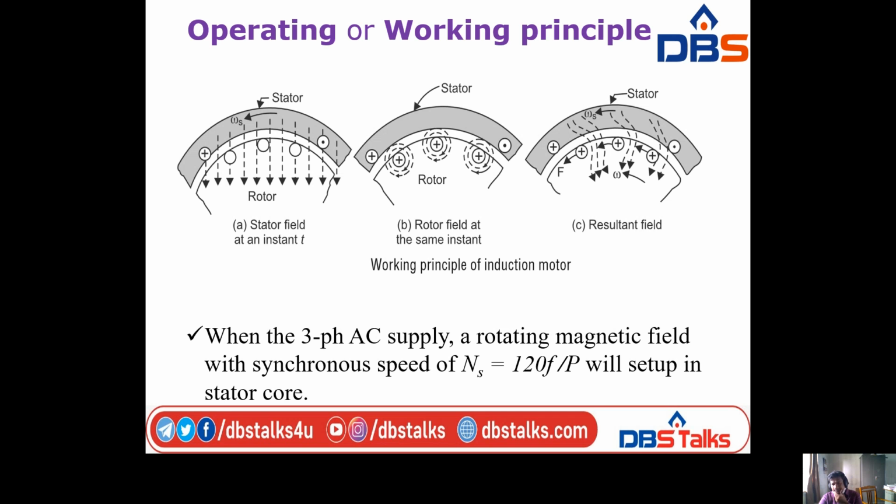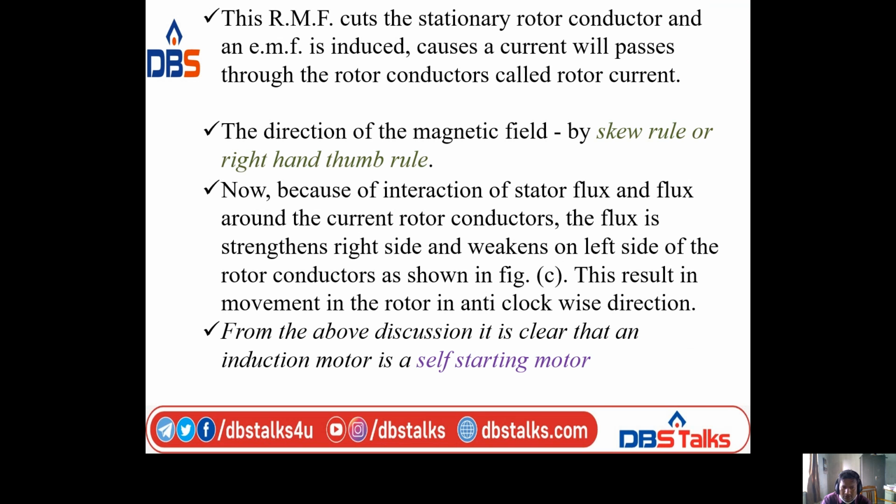Look at figure C, the resultant flux is strengthened on one side and weakened on the other side, right? So that is the point. This results in movement of the rotor in the anti-clockwise direction. From the above discussion, it is clear that an induction motor is a self-starting motor.